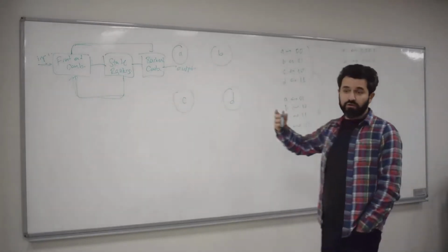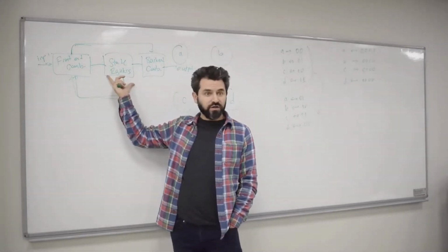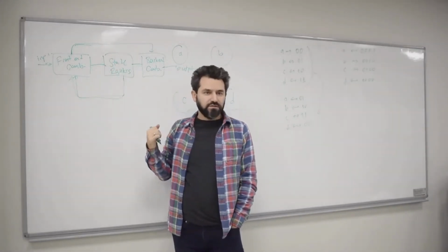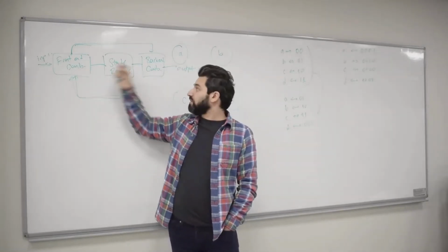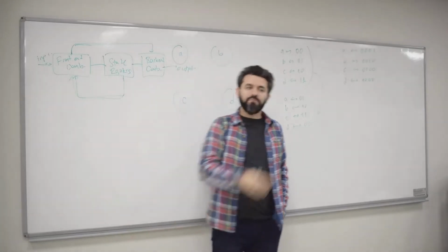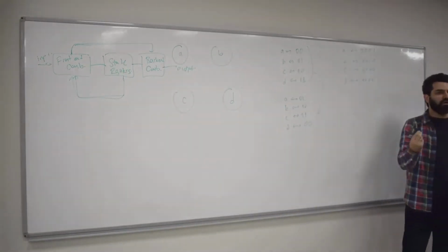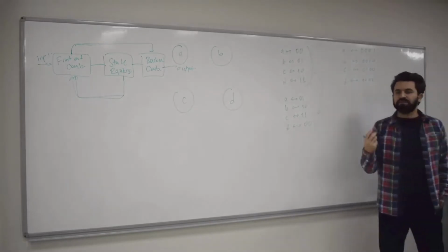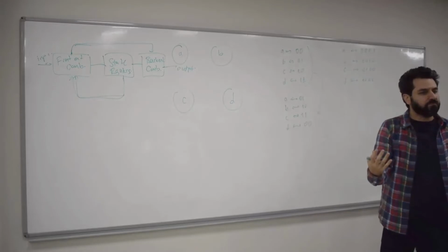Because here, for example, you need 4 flip-flops. So the state register complexity increases. But the gain that you get is the reduction in the complexity of the back end and front end. Typically, for the same design, for the same circuit, and when I say same, I want to express that it's the same specification.